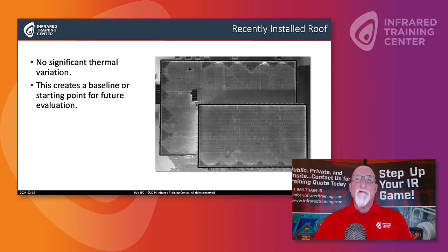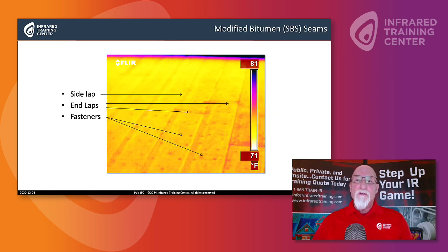What is the manufacturer looking for from me? He's looking to make sure that when the roof was laid down, the membrane has lapping material, and that the laps are not too large and not too small. We're also looking at the end laps, where we get done with one roll and begin the next roll. It's important to have a good 3 to 4 inches of overlap.